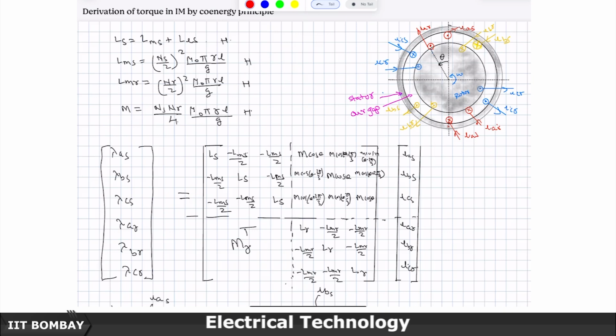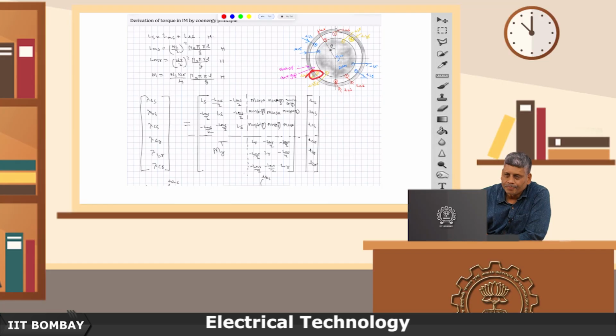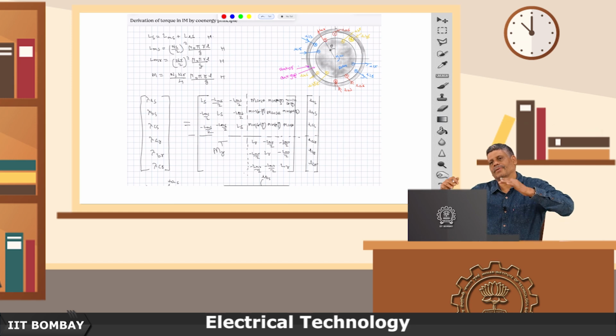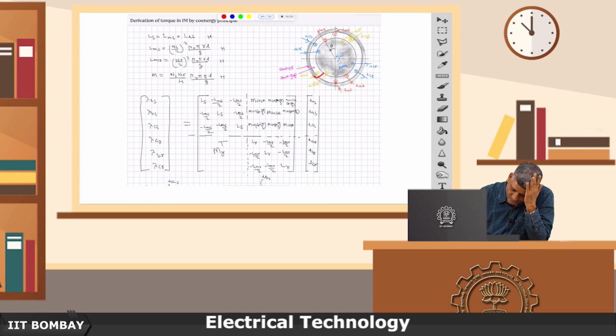Now, similarly 120 degrees ahead, you have a dot here, because this is my positive direction of rotation. So, the B phase or the Y phase, it is RYB or ABC. While drawing I draw it as RYB, while writing usually I prefer ABC. So, the B phase winding here, like the same dot, I have shown here also the same dot, because 120 degrees in space and 120 degrees, T by 3 time period later, this is how it will look when it is carrying its peak current.